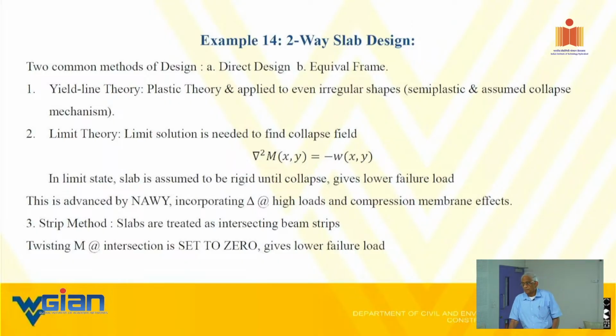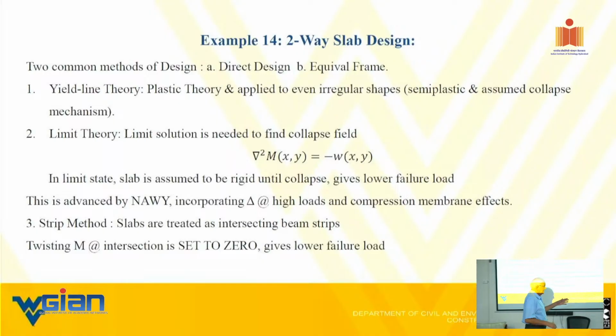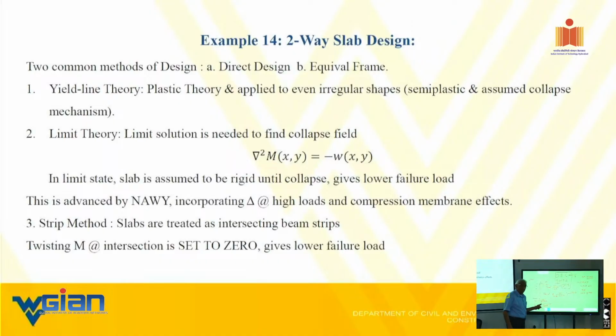No. I'm saying that for testing purposes, if you want to get the property of the FRP reinforced member, the ultimate moment of resistance will depend only on the concrete, not on the FRP. Yes. But we want to test the FRP. Well, that is the reason. Very, very simple. Is your FRP maintaining the original properties? Is your FRP maintaining the 60 ksi strength as a minimum after aging or not?